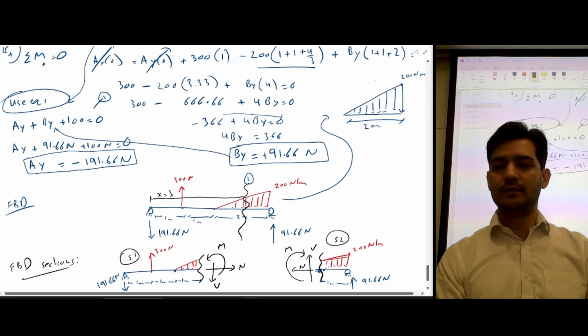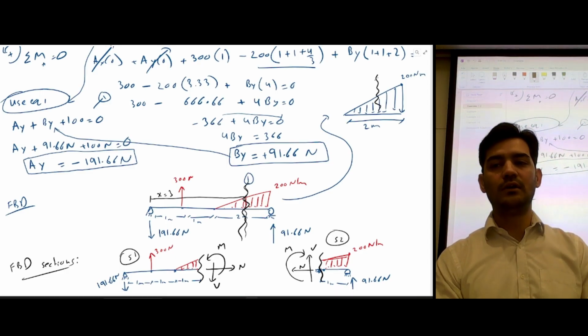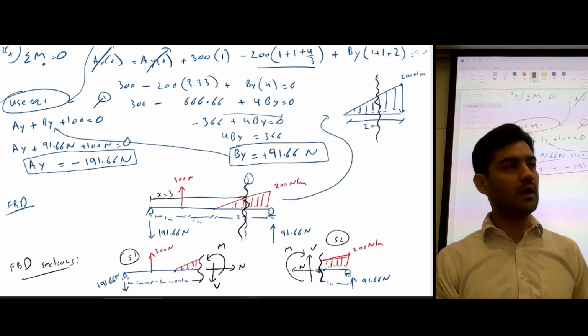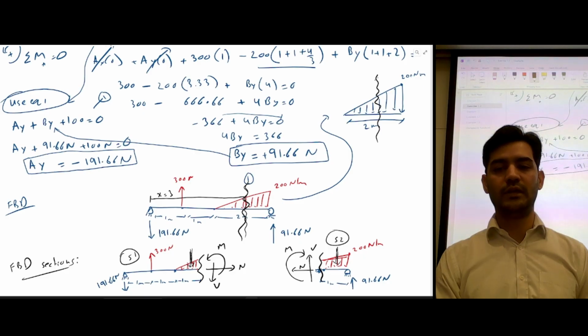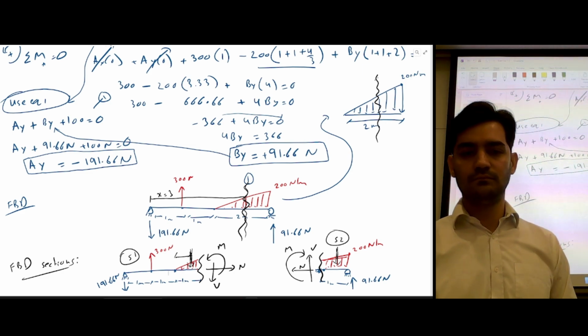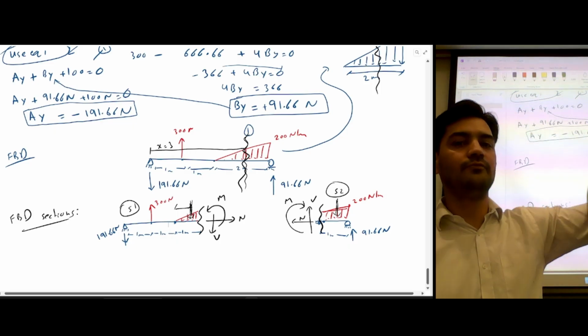Also, we can see the section was cut from here, so our triangular load also has been halved. So half goes to section 1 and half went to section 2. So we also have to figure out how to calculate the resultant loads in our situation. And also we need to know the centroids. We also need to know the distance for the equilibrium equations. Is that okay? I can move down.